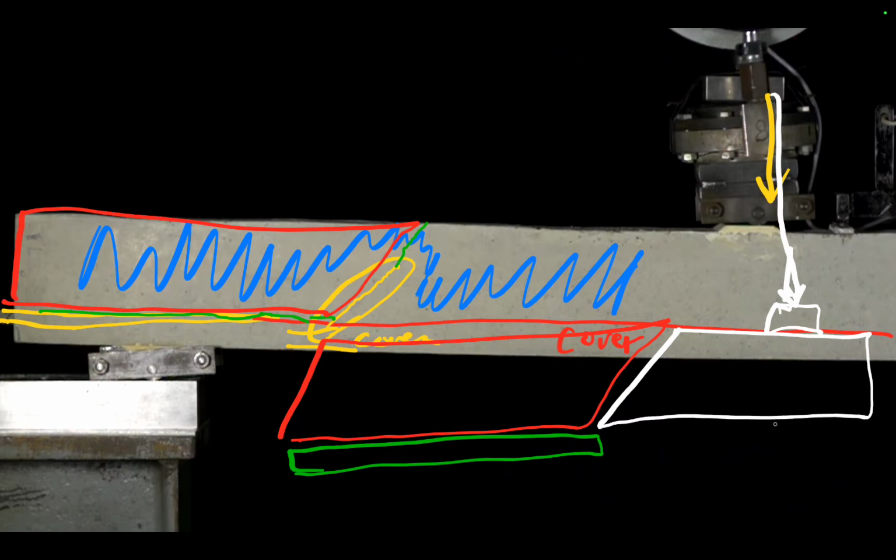And so as this deflects and goes down, deflecting down. Remember, that creates a bit of a rotation. This fracture is developing up. This one here is developing up. And remember, right there is at that point, that's your neutral axis where it transitions over from the fracture open side, the tension side, as it's mostly known as, with the compression side. That's the material that's left behind.